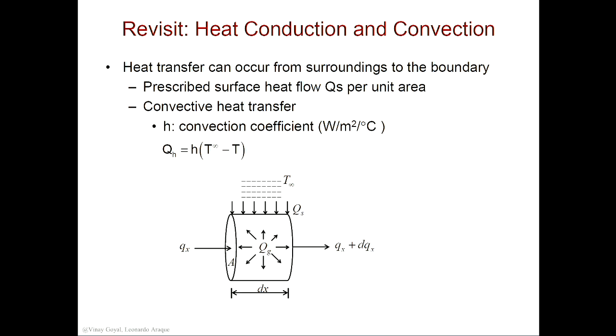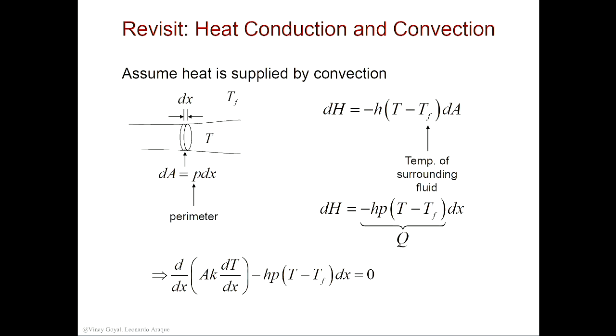And so here, if I try to study this problem for a one-dimensional bar, I'll take a small dx, and I can calculate the perimeter around this circumference, and around this perimeter I have a dx, and so I can now write the heat transfer due to this piece, this dx being exposed to the surroundings.